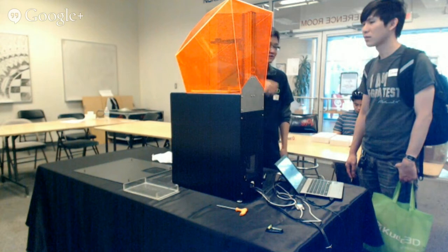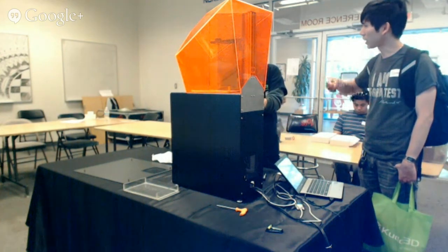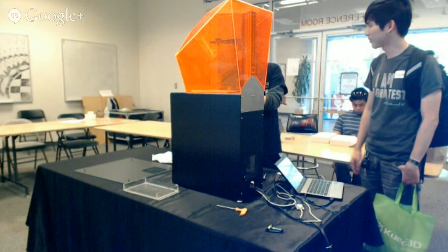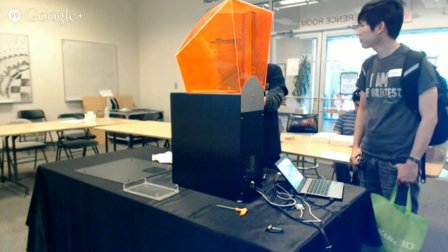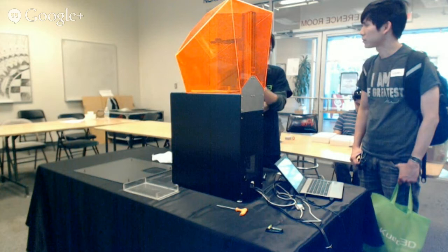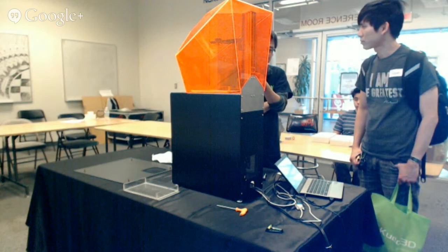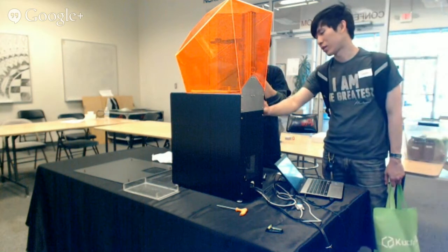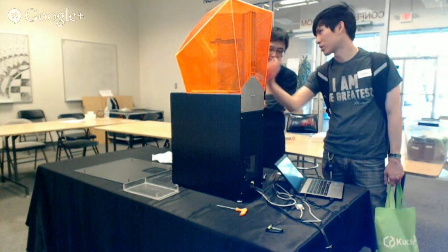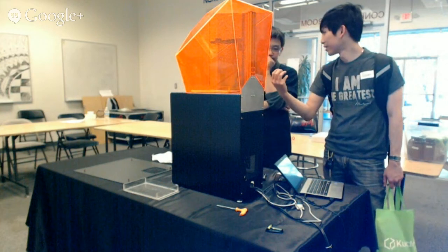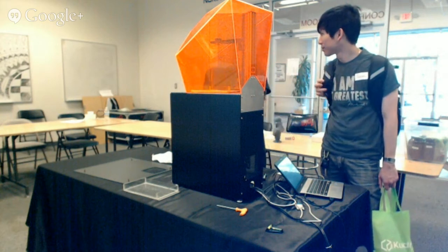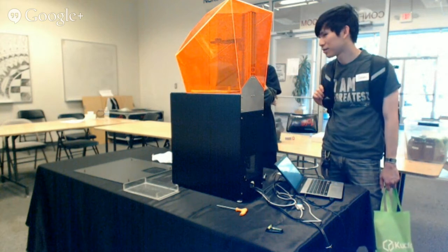The ratio between the 2 exposures is almost 3 to 1. The base layer is usually quite big because you want the first adhesion layer to be really hard, because you need it to stick to the bed very strongly, because that layer has got to withstand the sum of the separation forces for the rest of the life of the part. So that layer is going to be under stress every single layer.